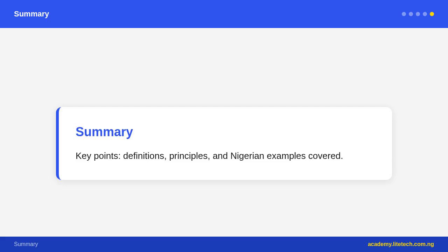Power in AC: P equals VRMS times IRMS equals IRMS squared R equals VRMS squared divided by R, same formulas as DC using RMS values. Rectification, half wave with one diode, or full wave bridge with four diodes, converts AC to pulsating DC, and a capacitor smooths the output.